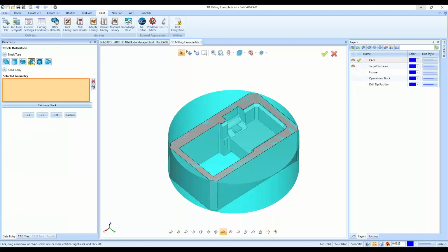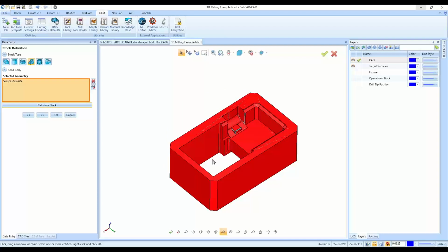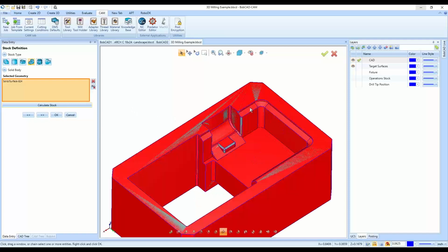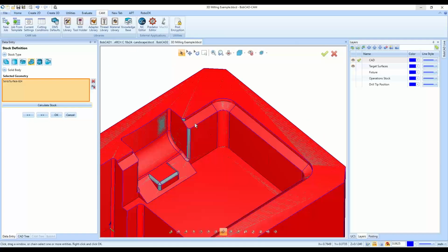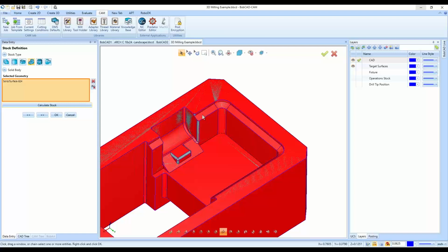This can be very helpful if I select an existing solid model, say if this was the casting of it, or if I have an additional 3D model of the casting, I can lay it over on top of this 3D model and select it here to let the software know the difference between the solid model I just selected and my workpiece. Say, for example, this is the area that's remaining, the extra amount in the solid model I selected. The software can understand that and mill out just the remaining stock that I've selected here.